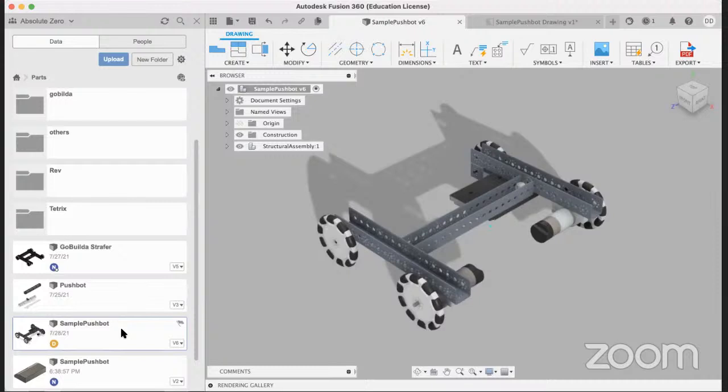If you start with a part that is not completely horizontal or vertical, let's say I imported this channel and I rotated it to some weird angle, now everything else that I import has to line up to that, right? So you have to be careful about importing and setting that plane, which is on XY. Start everything on XY, and then lining up all the other parts becomes easy.